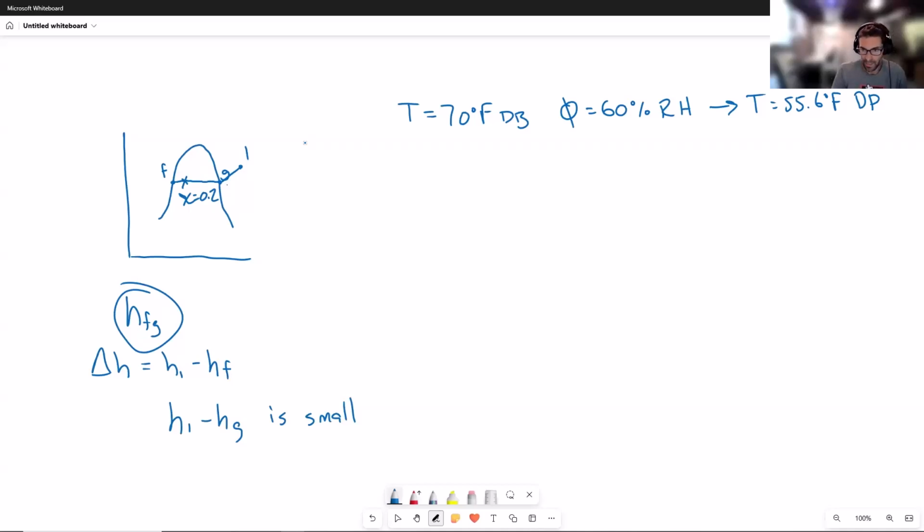And if we think about what's happening psychrometrically, that inside air, we'll call that state 1, we'll just arbitrarily put a point here. Some of that air is going to come into contact with the inside surface of that glass, and the glass is going to be colder. So that's going to cause it to cool. And as it sensibly cools, it moves horizontally to the left. So the humidity ratio isn't changing, because it's a horizontal line. There's no change in the humidity ratio as the dry bulb temperature is reduced.